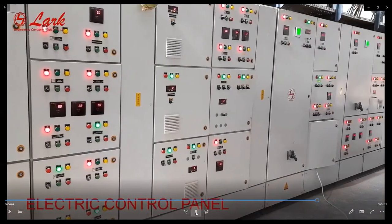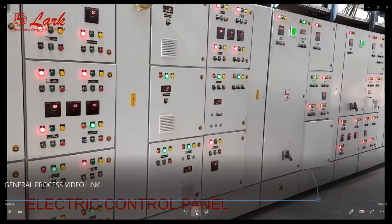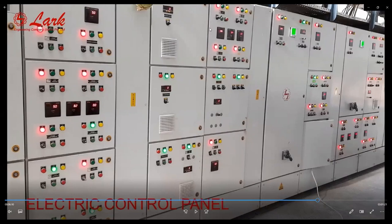Then your electric control panel must have all the features like single phase and double phase prevention, and a reverse RPM prevention system should be there. The rating of the starters and the contactors should be as per the matching of the screens.